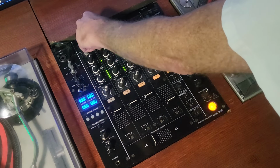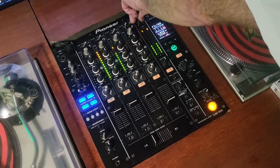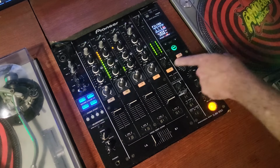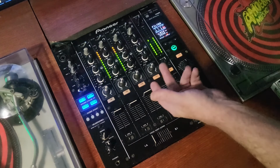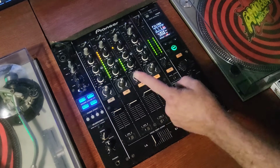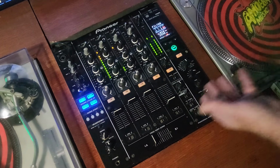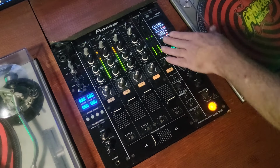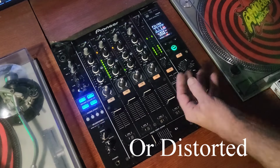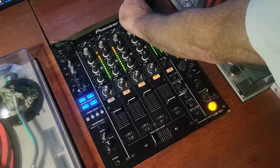You want to crank these up. Let's say you want to crank them up here, and then adjust your master accordingly to hit 0 dB. Yeah, you can do that, but the problem is you're robbing your master output of a clean signal. Does that make sense to you? It may or may not, I don't know, but when you make any other adjustment, something's getting robbed as far as clarity goes. And if you want good clarity, you want to give everything as much as possible.